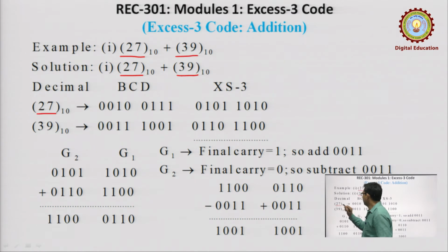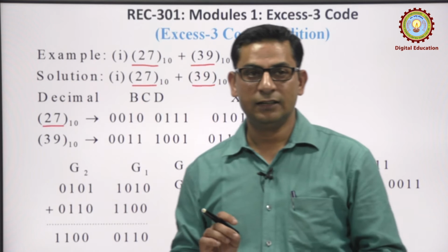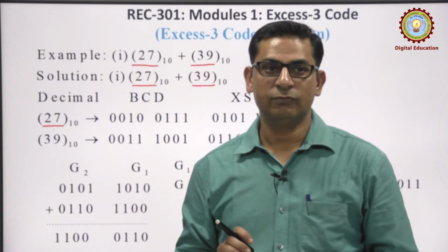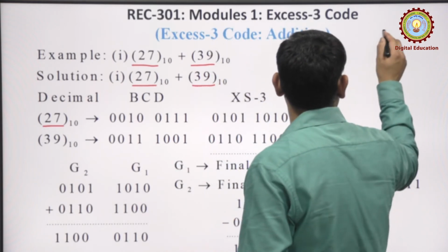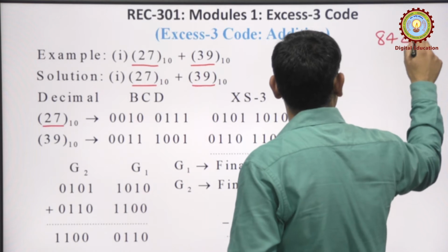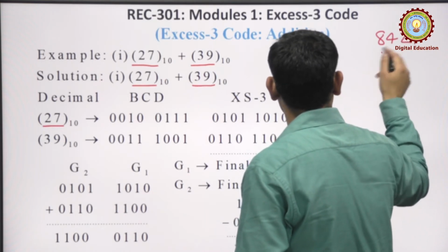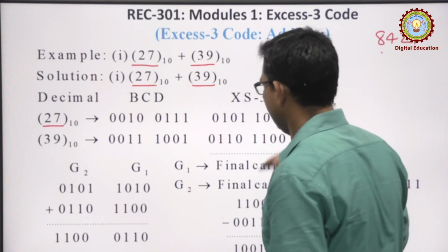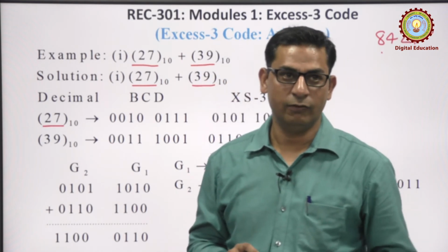The BCD code represents each digit of the decimal number in a 4-bit code, and the standard weight for the 4-bit code is 8421. This is the standard weight for the BCD code if the code is not given. This is the default.